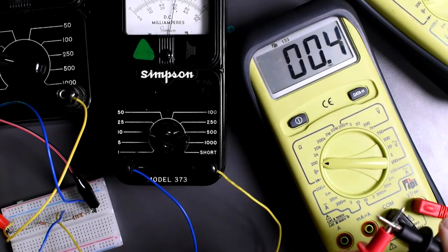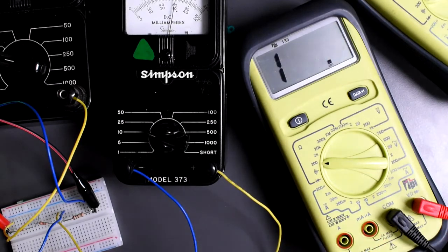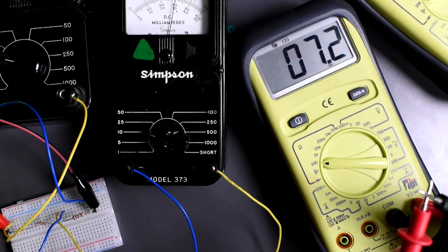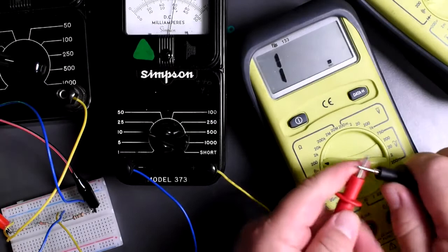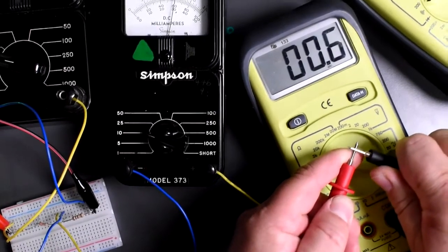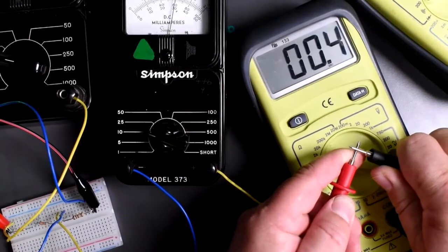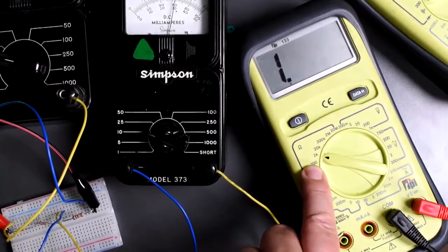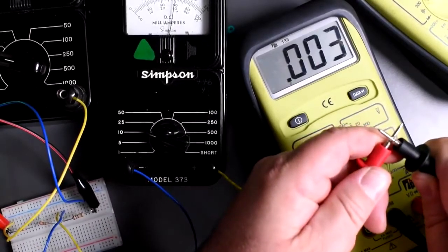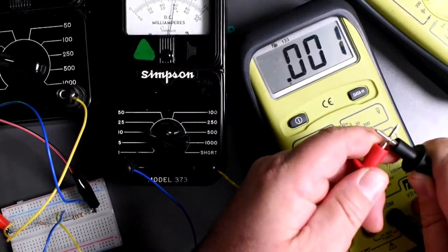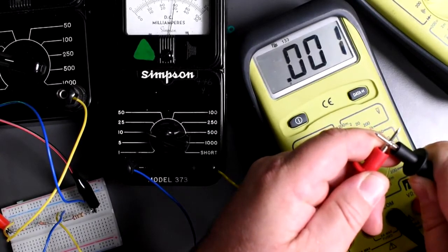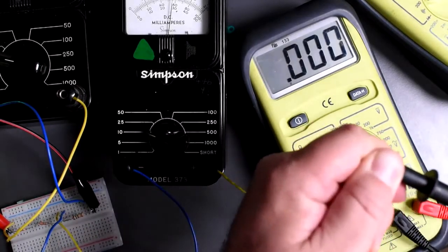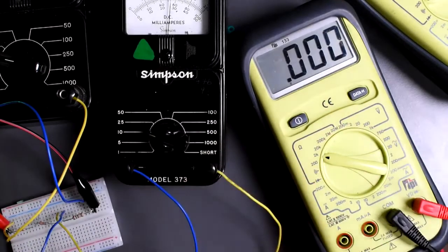0.6. It should show us 0 ohms, but there's a certain resistance in the lead, and maybe there could be certain resistance between the contact points. Maybe there is some oxidation happening. See what happens if I just rub those together to clean those probes. 0.5, 0.6, see, we got it down a little bit. But if we select the 2000 ohms range, that should show us pretty much 0, right? 0.01, a 100th of an ohm. If I hold it tighter and rub it together, then yeah, we got 0 ohms.